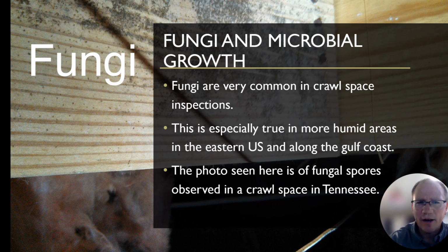But I just wanted everybody to know, really look at the floor joists, look at areas that might have fungi like this. You can even take your finger and smear across them and see if those fungal spores smear, then you're definitely going to know they're active, whereas they could be dead if they don't smear. But again, if you're seeing them, it's better to err on the side that they are active and is something you need to look at performing treatment for.